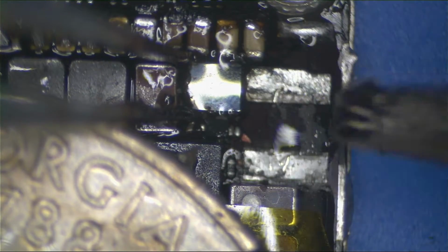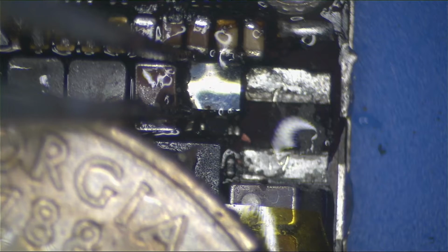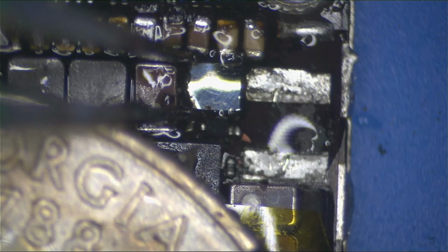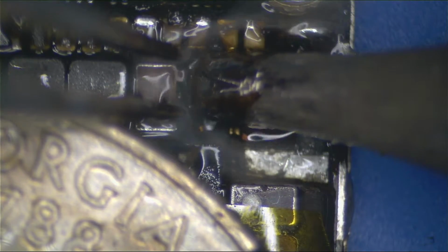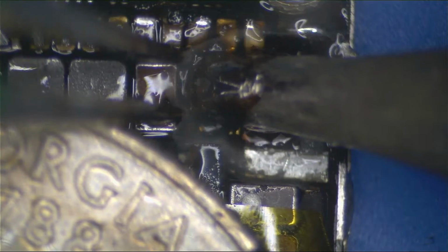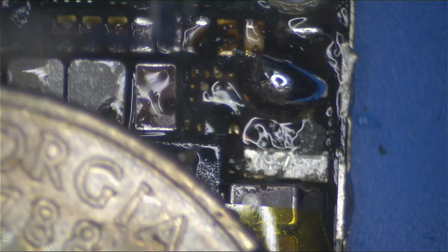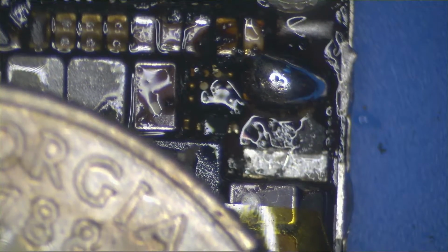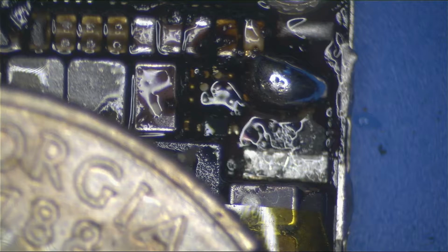I'm going to show you the tip of my iron actually. Hint, hint, JK. No, yeah, so that's a T15 D2 tip. It's a 2 millimeter wedge tip. I love it for this job. You can use any, really you just need a big tip. So what you do is just touch the top of the IC like that, have some solder on the blob of your tip, and bam, you just pop the IC off. Just grab it with your tweezers, and once it moves, just lift it right up with the iron, and it'll come off perfectly clean.